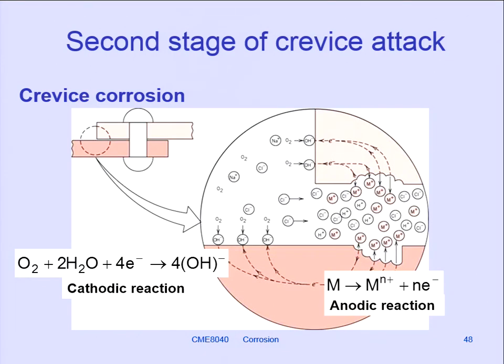So this damage here is actually pitting and crevice attack on the inside of the wing, coming out through and beginning to appear as blistering of the paint on this surface. And then of course as soon as the paint coating breaks down, there'll be more attack from the outside as well. Why am I showing you that?